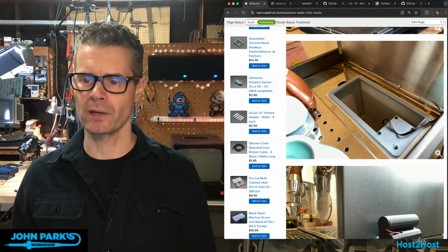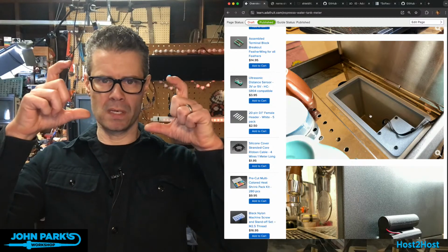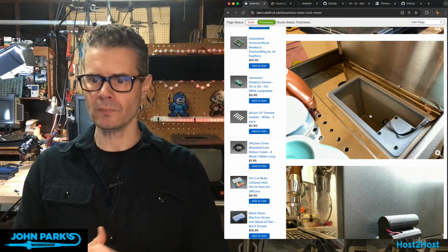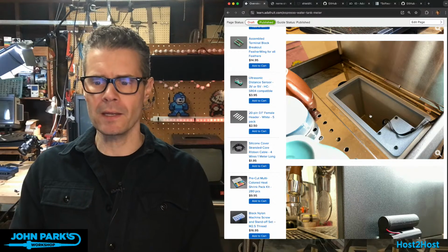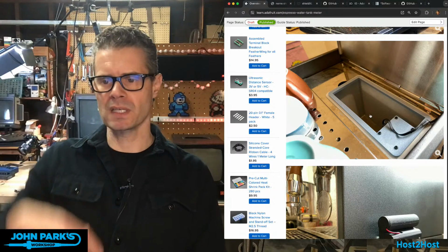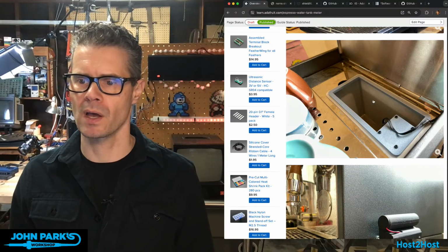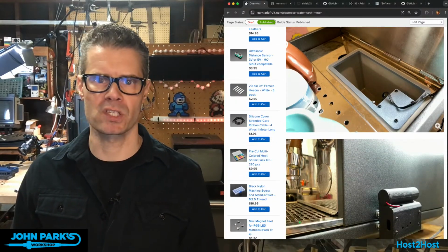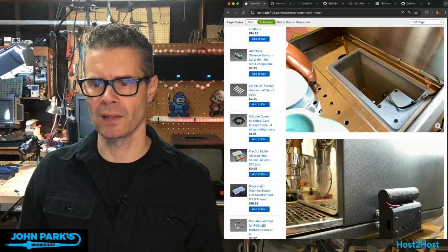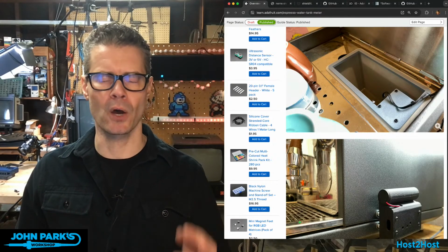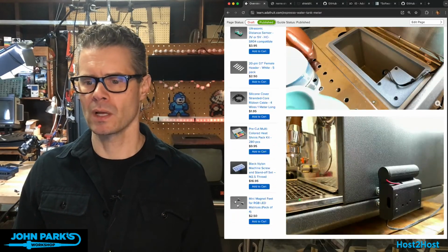There is my final design on the tank sensor bracket. So we have the ultrasonic sensor pointing down. There's my little silicone ribbon cable to keep it small, but give us the power, ground, and the two data lines that we need for trigger and echo running along the side.